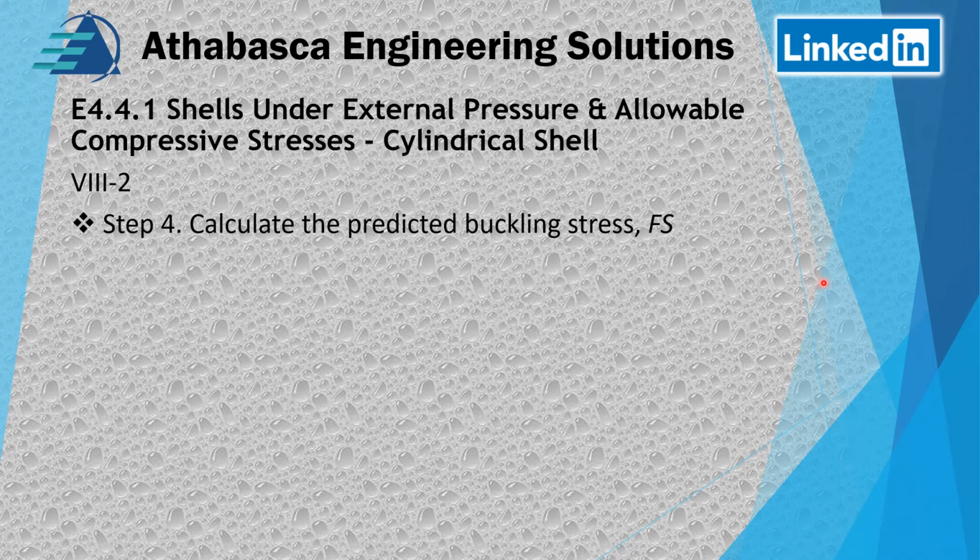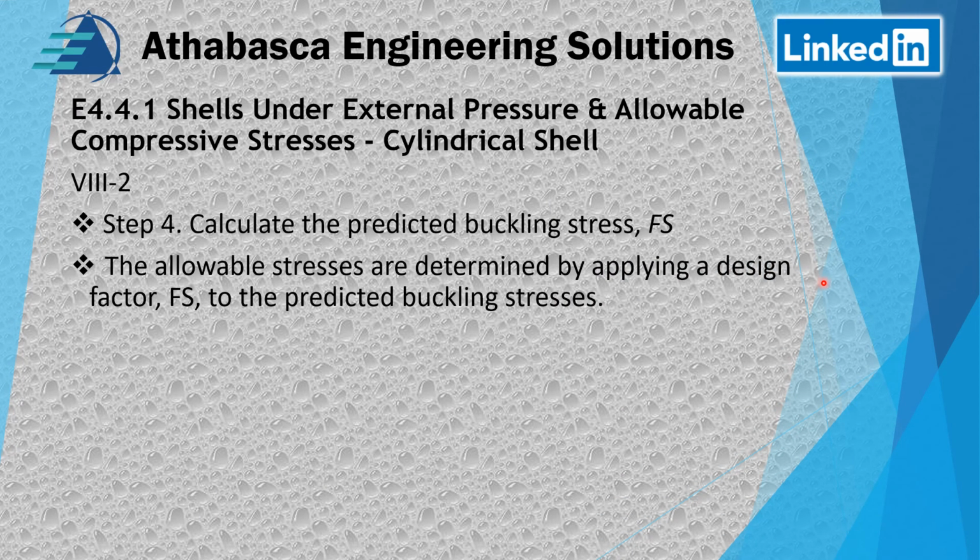So last step is we're gonna calculate FS, right? It's our design factor. Some standards are trying to get away from design factors and go using like allowable stresses. But anyways, this has not changed. The previous step 3 has changed after 2017, but this has remained the same as far as I know. And basically, FS is 2 if we've got buckling stress is considered to be elastic.